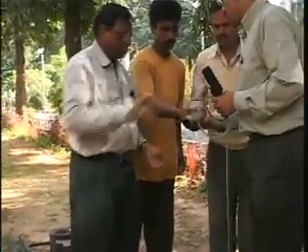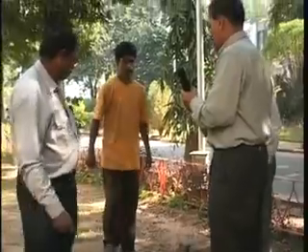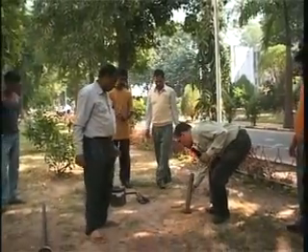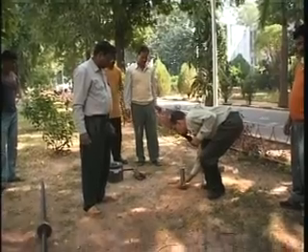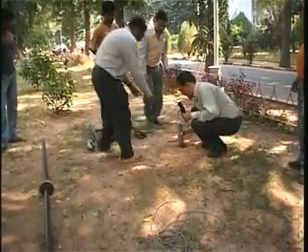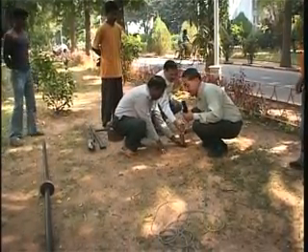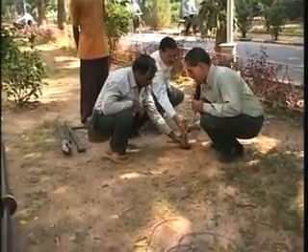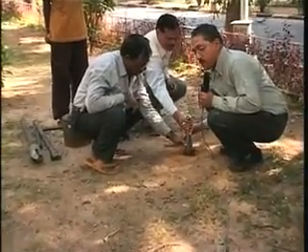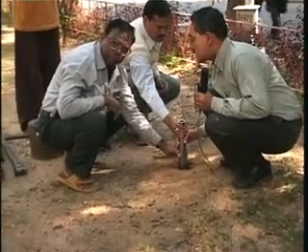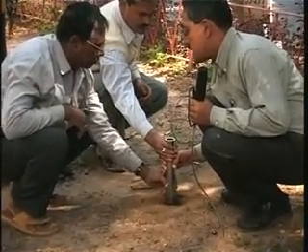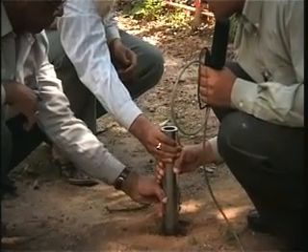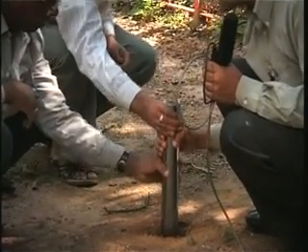And what we are going to do, we are going to drill a hole in the ground, and we just lower the sampler to the depth drilled and drive it, connect it to the hammer, SPT hammer, with the standard rods, and drive the assembly with the standard SPT hammer, as you are going to see in the next little bit.